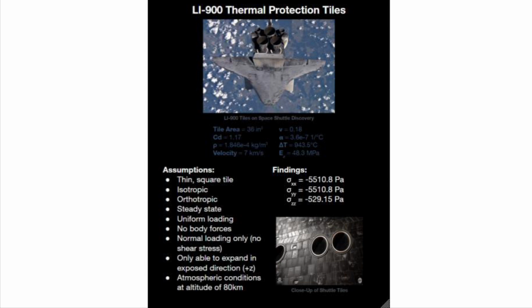And finally, to the right of that, we have the final results of our findings. Assuming no shear stress, we found the axial loads on the tile to be 5,510.8 pascals of compression in the x and y directions and 529.15 pascals of compression in the z direction.